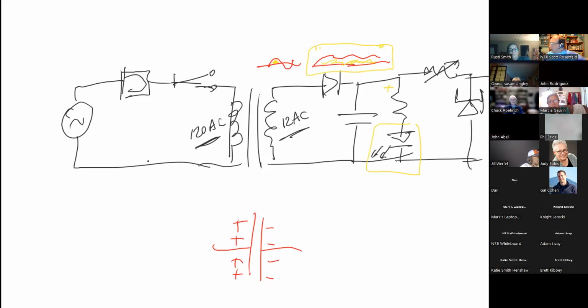All right, element 9 right here. They label it as element 9. That's a variable resistor or a potentiometer. And finally, the purpose of the resistor is to limit the output current of the power supply. Again, by changing that value, that determines, even if there's a short circuit on the output, there's a little bit of resistance that we've thrown in to limit it.